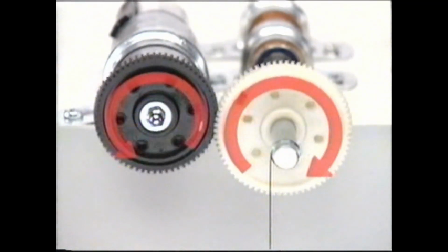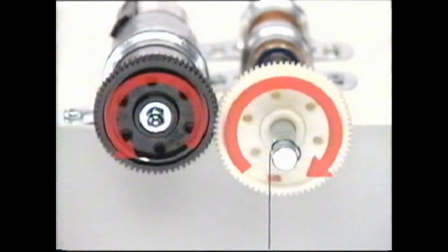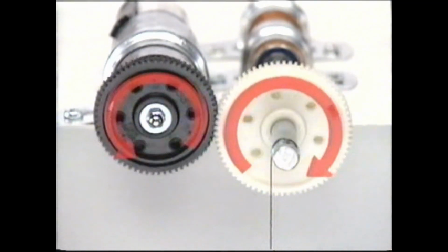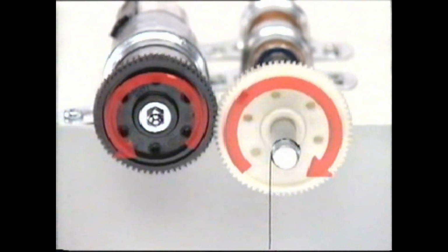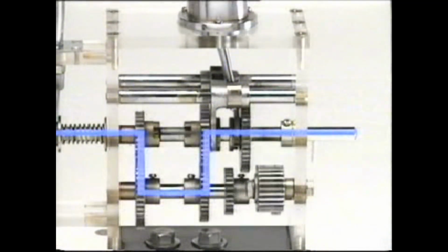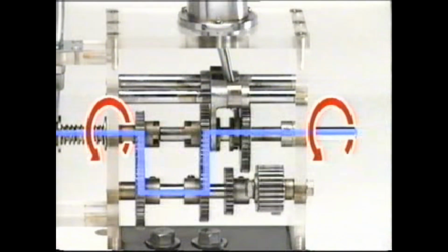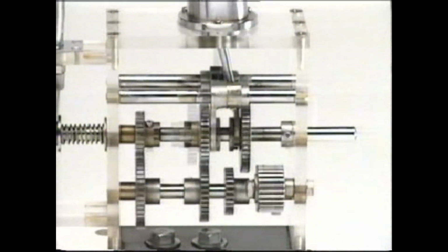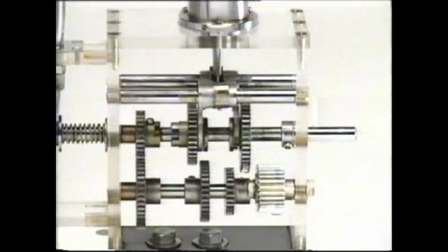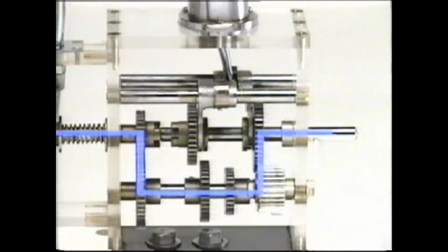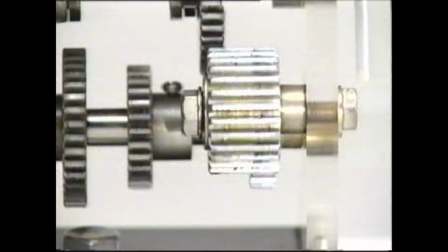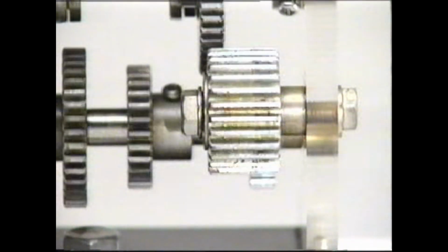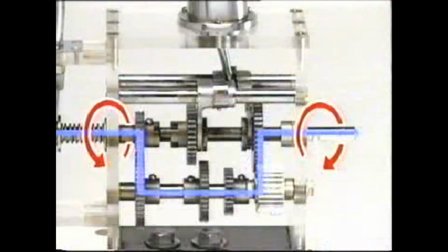With a combination as shown in the previous models, the rotational direction of the force input side is opposite to that of the output side. Therefore, in practice, two combinations of gears are assembled to obtain the same rotational direction. Since driving the wheels in reverse to back up a car is one of the functions of the transaxle transmission, one play gear is added to compensate for the engine that cannot reverse.